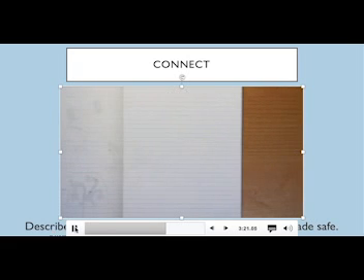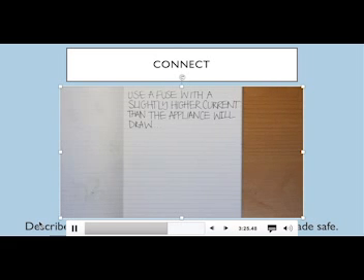There are different ratings or sizes of fuse which will blow at different currents. A device should have a fuse rated slightly higher than the maximum current the device will draw when it's working normally.